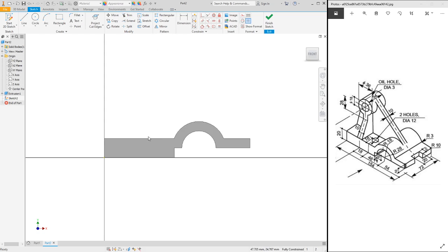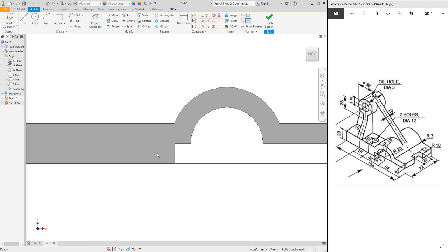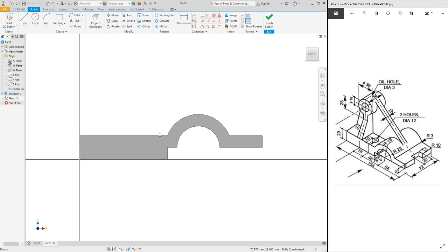Now when it comes this way, there is no area on this object that we can use as our reference point. To be able to have a reference point so that we can have this drawing done on it, we need to first of all bring some edges of this onto the work plane so that we can draw from it. So we use this one here on the modify toolbar. We have what we call the project cut edges.